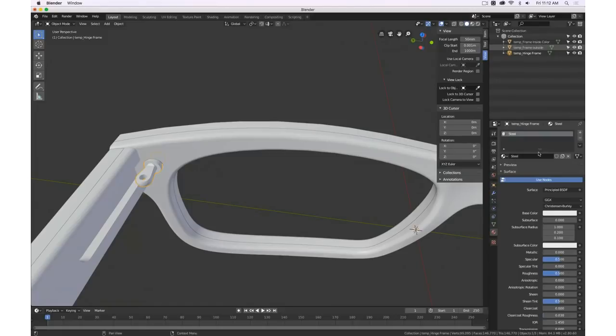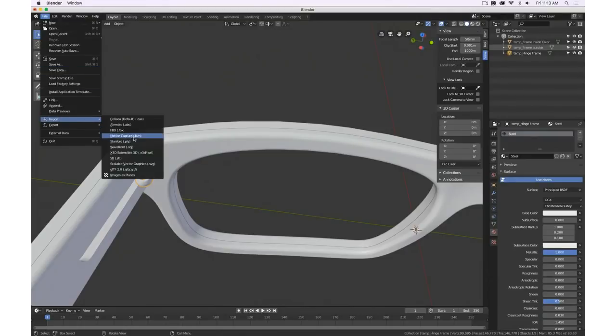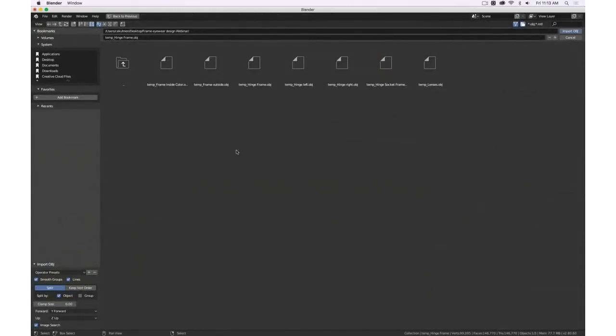So this is metal. Metallic reflections are different. So specular I set to 0, and I set metallic up. And let's keep roughness down. For all the settings here right now, because we only have a short amount of time and this is a basic introduction, I really go through the basic elements. If at one point you guys have more questions, feel free to contact us or me, or also go to the Blender website. But I hope that with this introduction, I will show you this is actually a pretty easy process.